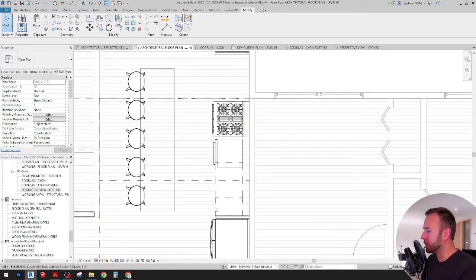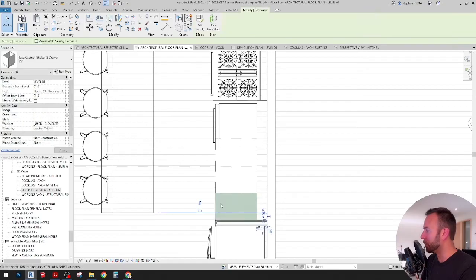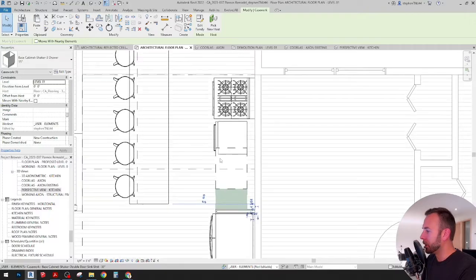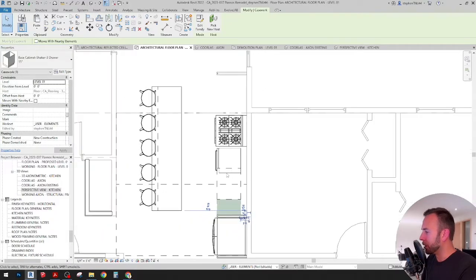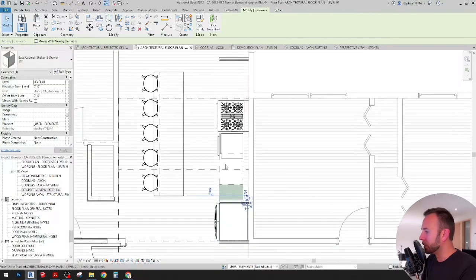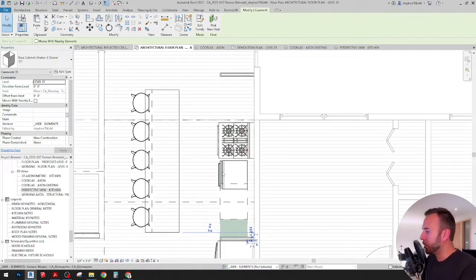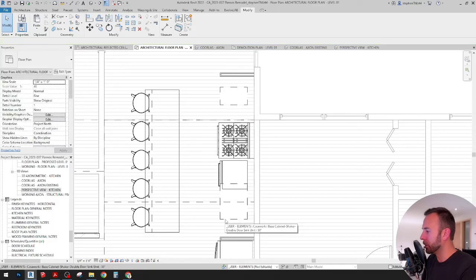So especially in this case, I don't really like to go less than 15 inches. Typically your utensil trays are going to need at least 15 inches in width. So we're going to try and leave that as it is. But you can see I'm already running into a bit of a tight space between all these elements here. So we can forego the utensil cabinet on this side and just swing that over to there for now.